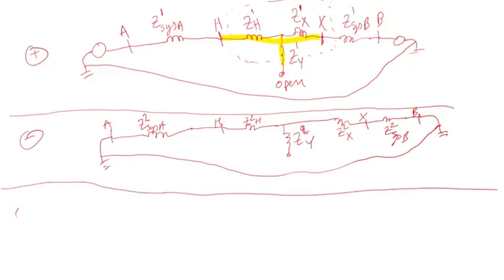Now, let's draw the zero sequence impedance. The zero sequence is a little bit tricky. And again, positive and negative sequence impedance, when you do the T model, so this is basically just a transformer. The equivalent T model for the negative sequence impedance, and you see it's open. So basically, the tertiary branch, it's like it does not exist.